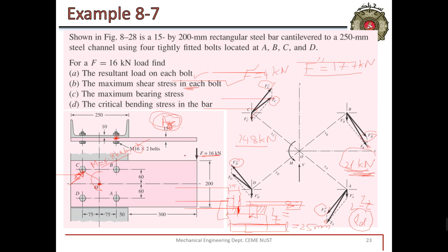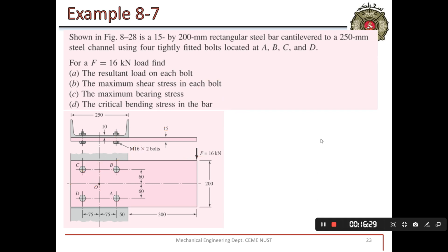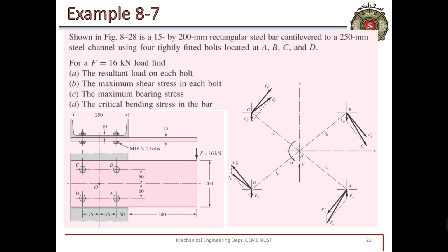For bearing stress, for the same figure, what is the maximum bearing stress? This is the area. The acting force divided by this area, which is the thickness, 15 mm, times the diameter, which is 16.